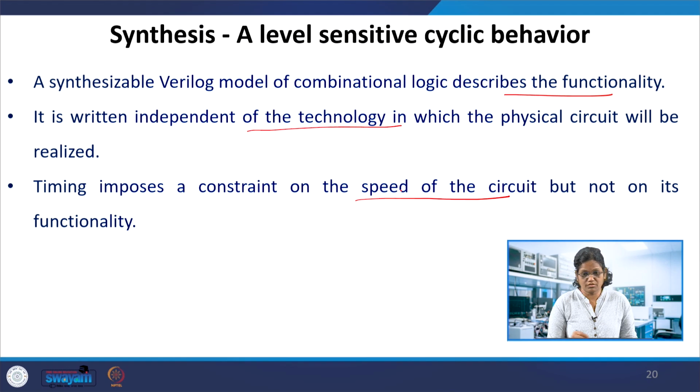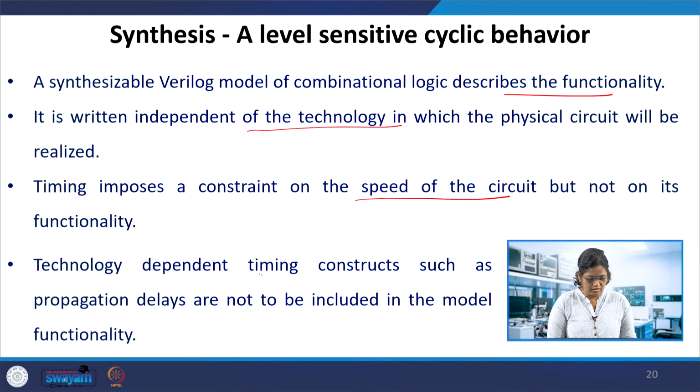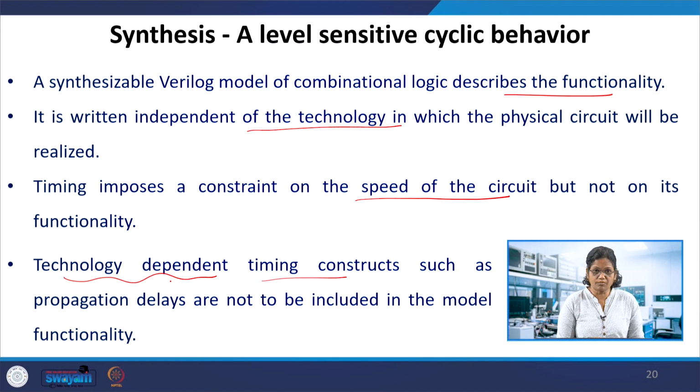Functionality is not tested by it. If you recall the HDL design flow also, the timing analysis and the functional verification are exclusive. When you do the timing, 1 or 2 input cases can be given and tested for the functionality after the timing analysis. And in the case of timing constraints, it is purely the timing one, and the delays related to the gates and other things, the technology dependent timing, should not be included. For that particular technology, the delays for the gates would be different, so that need not be included in the code for the synthesis.